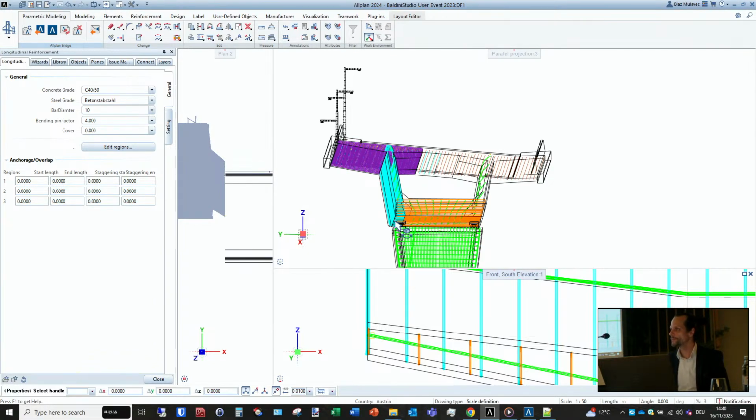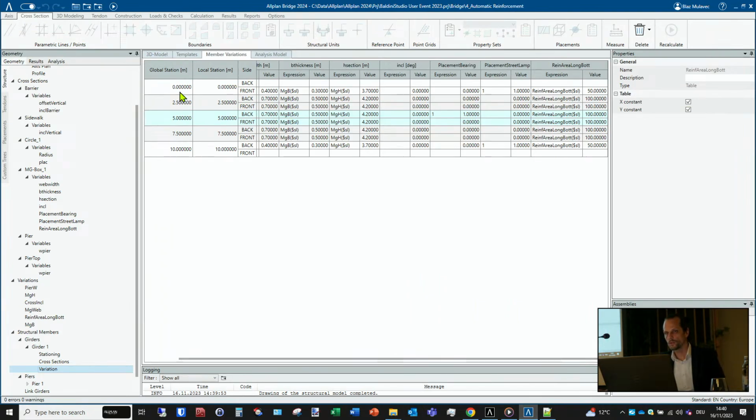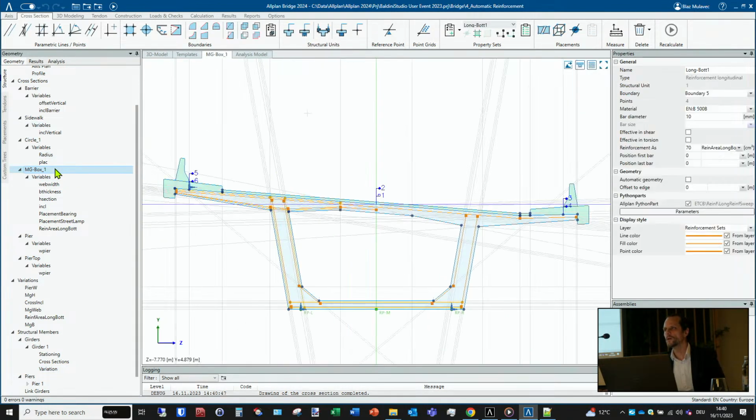For example, now this is automatically one layer of reinforcement, which follows the curve of the bottom part of the bridge. Can you do the second layer only in some segment above the bridge, and how does this influence the necessary reinforcement amount that you show us in the table? If you do the second layer manually, is this updated?